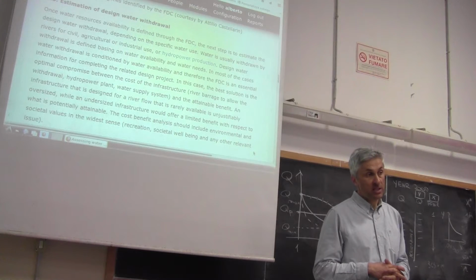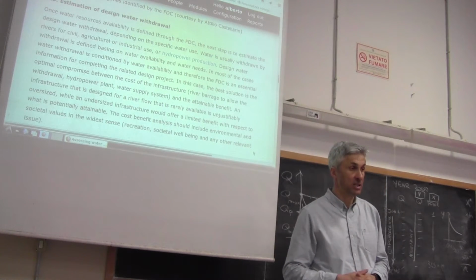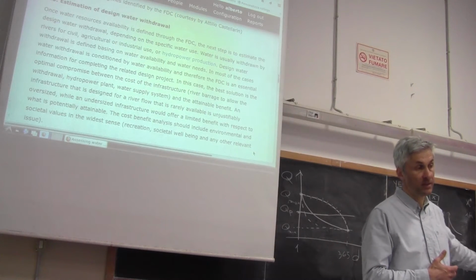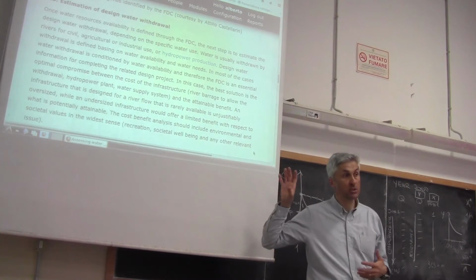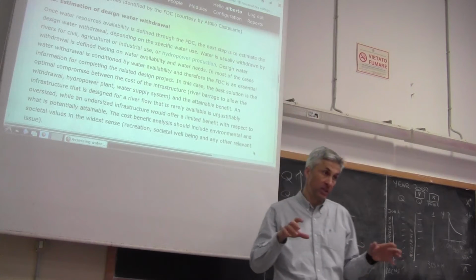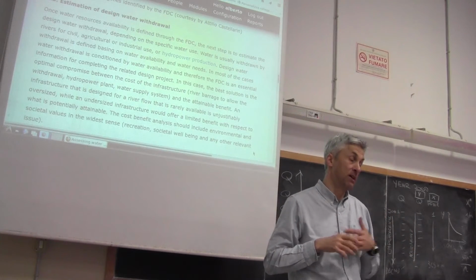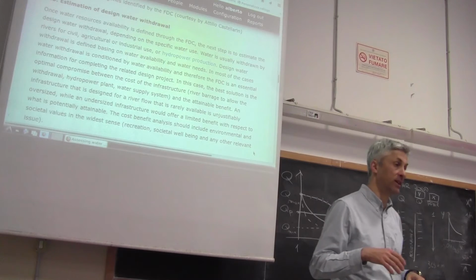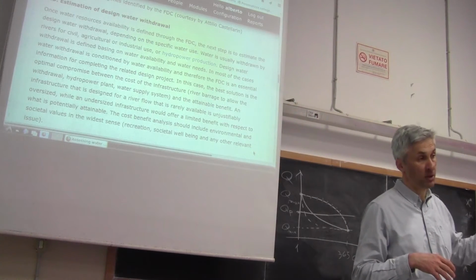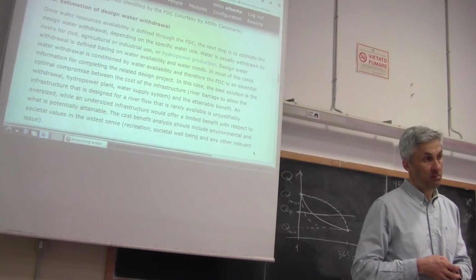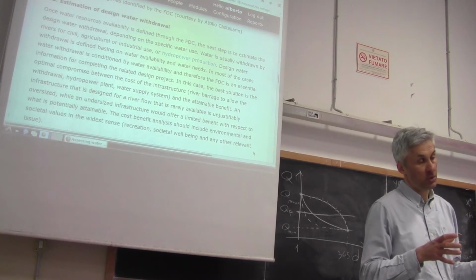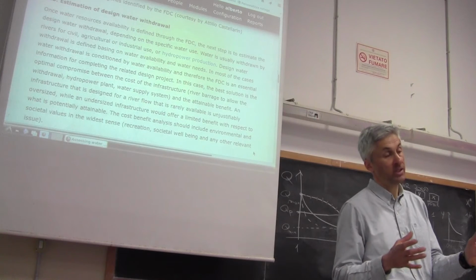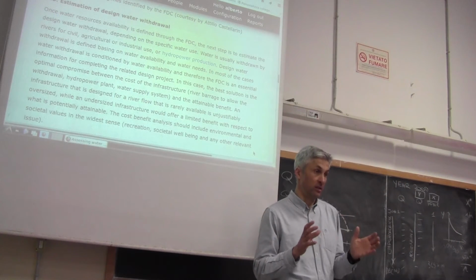And therefore, in most of the cases, if you are asked to make this analysis, if you are called into play, the problem is that you have demands that are higher than water resources availability. And therefore, we are conditioned indeed by water resources availability. We are conditioned by the need of taking as much water as possible, without negatively impacting on the environment, without overexploiting water resources, of course. This is why we focus on estimation of water resources availability to design water supply systems, to design hydropower plants, because this is usually the conditioning factor.